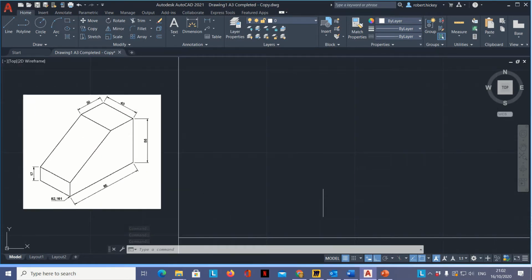That's no problem. Now, we want to draw the other lines going on the left and the right, the ones going off at the angle. So a 3D drawing like this, it's always drawn at an angle. If you were drawing on a drawing board, you'd use the 60-30 set square. So what we do down here in the toolbar along the bottom, we can see we hold the cursor on there. It's the isometric drafting pane, and that's what we're looking for, and it's off at the moment.